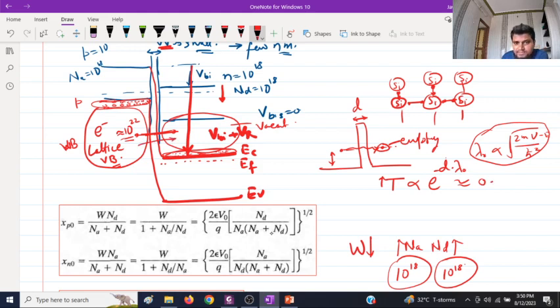Even if only 10% of them are tunneling, there are a lot of carriers, right? A lot of 10 to the power 22 carriers are over here. Even if we assume it is 10 to the power minus 3, then there will be 10 to the power 19 electrons tunneling through this junction. And that's why the tunneling current increases, because the electrons are actually tunneling from this side. So the effective current will be from N to P side. Of course, in conventional current, we have ID over here, so the current is basically flowing in this direction.